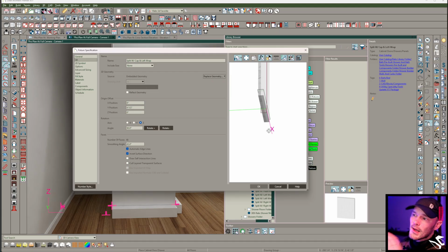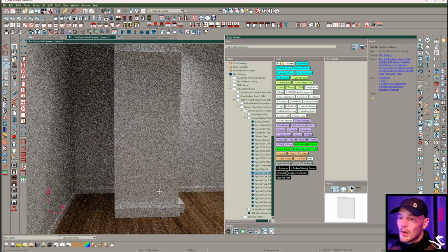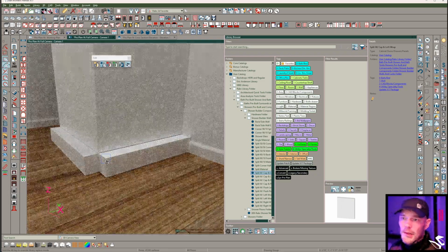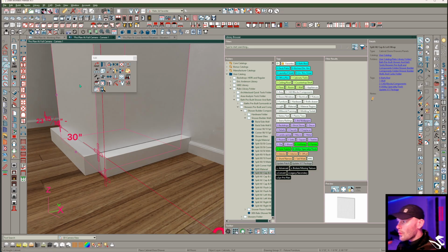So we're offsetting this Y position. And why would we do that? Well, very specifically because look, these don't meet up at a corner, so they needed to be offset in the Y so that they're pushed into this cabinet assembly. That's how this system is built. And very simply, the rest of this is just component based. Now, I'm not walking you through this step by step per se, but I'm giving you all the tools that you would need to recreate this.